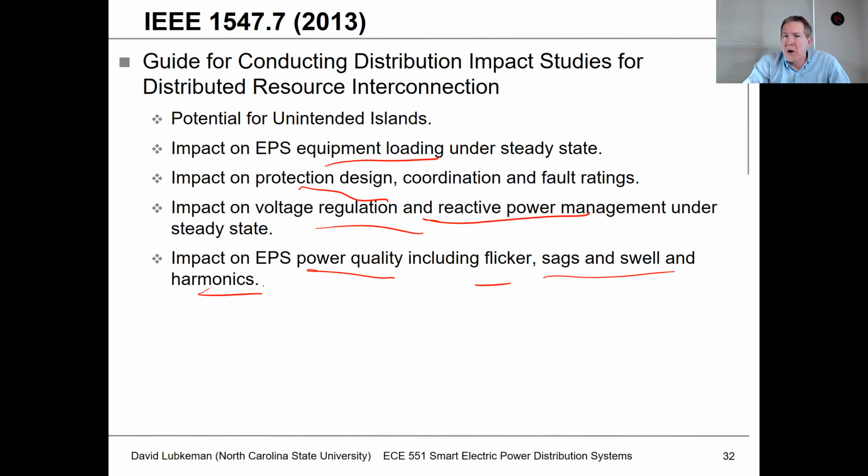Initially, we had a lot of smaller units. What I mean by small is hundreds of kilowatts and megawatts. Now we're seeing at the distribution level, maybe up to say 20 megawatts. So not only are we getting more experience based on past projects, but we're also seeing the impact of very high penetration levels. And we're taking this knowledge and factoring it back into the thresholds we use in our studies. And so 2013 is a pretty antiquated standard, especially given that with the 1547 2018, these inverters have a lot more capability that we can include in our modeling.